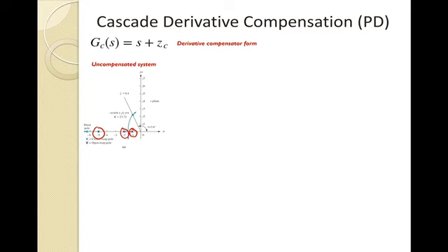Okay. So this would be our plant transfer function, and then initially what we're showing you on this graph, the uncompensated system, you can assume that this G sub C term right now is 1. It's basically not there, and I have this G of S. So we have our open loop poles, and as we change our gain, we could get our closed loop characteristic. So how we get our closed loop characteristic, that would be our T of S. Okay. And what I will do is write that down. So basically we'd have this term over 1 plus this term.